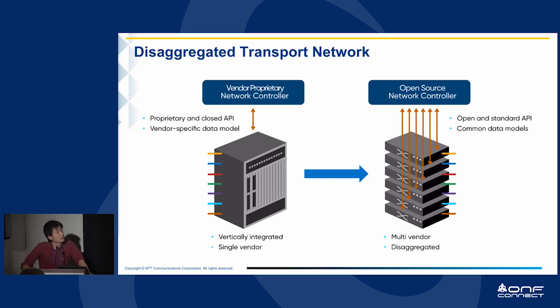And what we are going for is the right side, where all components in the ROADM are fully disaggregated, and each component has an open standard API and common data models, so that in addition to avoiding vendor lock-in, we can do software integration of these disaggregated components much more easily than with the legacy one-type ROADM system.